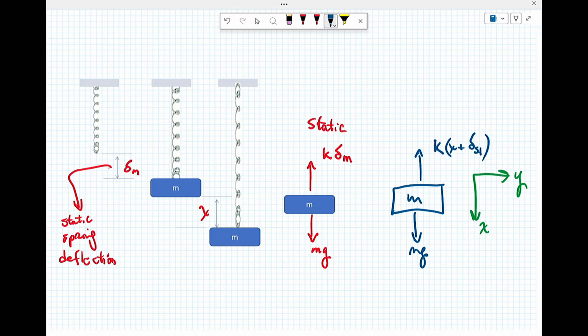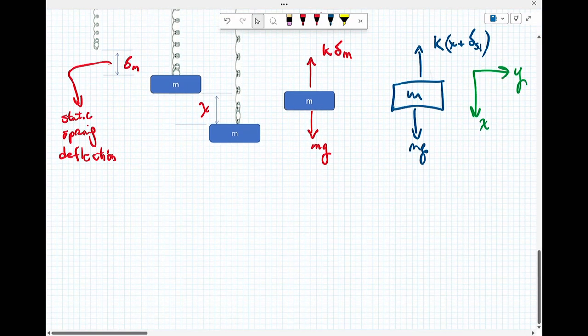I have the deflection of the spring from the point of where I released it. So I displace it a small amount, and then it's going to start vibrating. So it'll move back and forth. It never stops. At this point, there's nothing to damp out motion. And so if nothing can damp out motion, the solutions that you see are always going to be nicely repeatable.